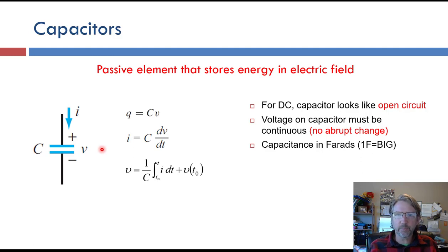These are the equations that we will use through the whole class here. These two down here, I and V, we're interested in. We don't care so much about charge, although it is deep in the physics there. So here, the current through the capacitor is the capacitance times dV/dt. So here, changing the voltage, like we just said, gives you a current. This is like Ohm's law, except it's a differential equation.